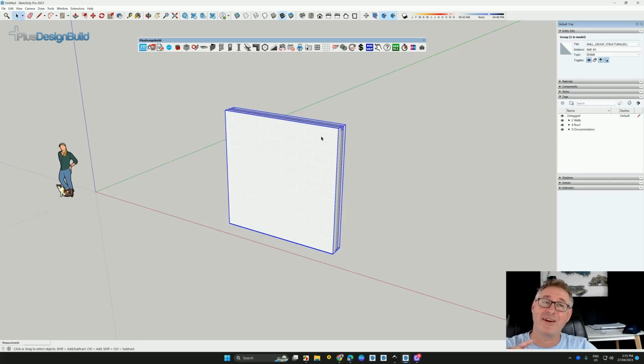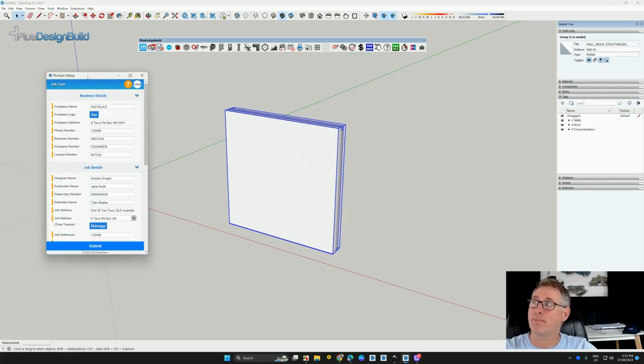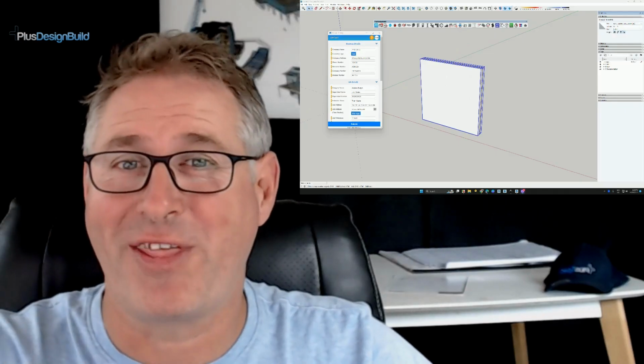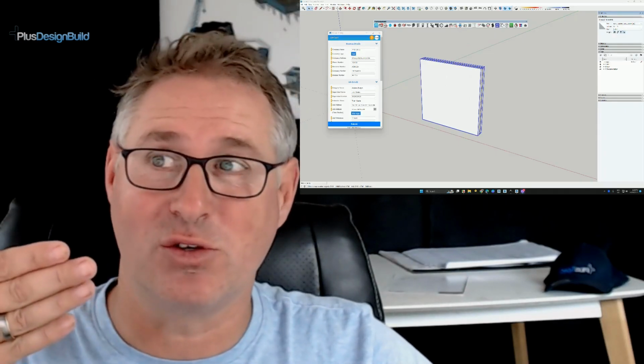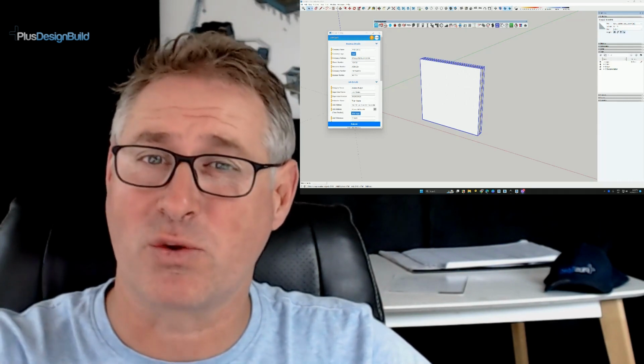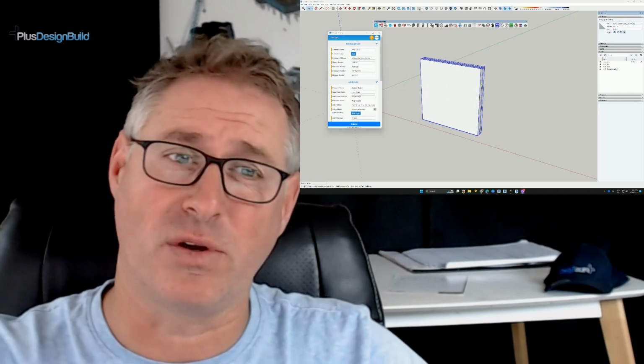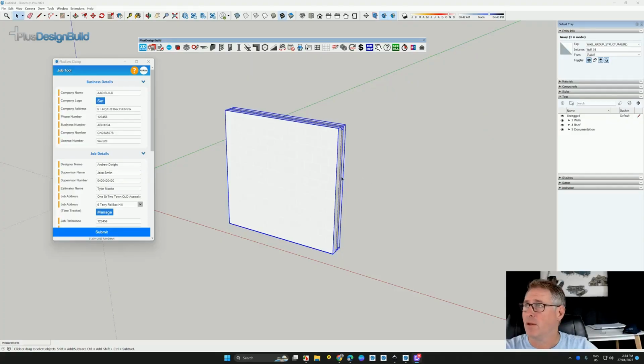There's one thing that I didn't show: before I did all of that, I actually set up my PlusSpec to know what units of measure I wanted to quantify. It's so important that if you're going to quantify in lineal feet or square feet, you tell PlusSpec that that's how you want to do it. So let's have a look. I'll close it, but I'll open it again.